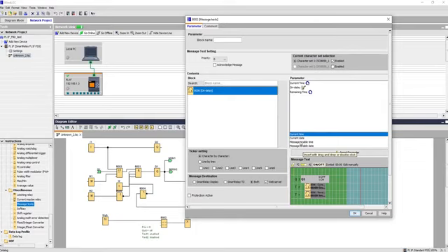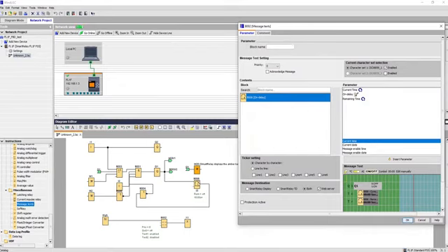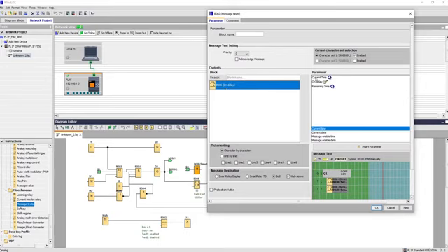Apart from that, we can even showcase the inputs and outputs, the values or the status of those as well. Since we have already considered a timer over here, that is the B006 block, an on delay timer, in this timer we have three different types of parameters which we can view on the FL1F Smart Relay screen. I have considered the timer current value and the timer remaining value. For that, I'll do one thing, I'll just delete all this.